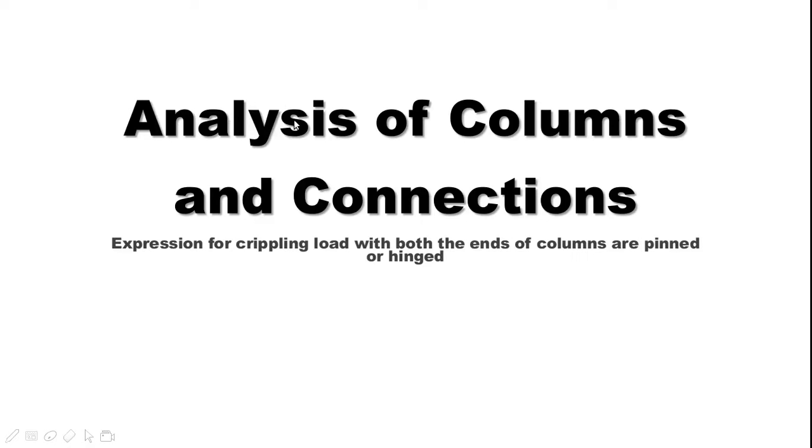Good morning. Today is lecture 2, analysis of columns and connections. Lecture 2 covers the expression for the crippling load when both ends of the column are pinned or hinged, and all three conditions. Here, the first derivation: the expression for the crippling load when both the ends of the column are hinged.